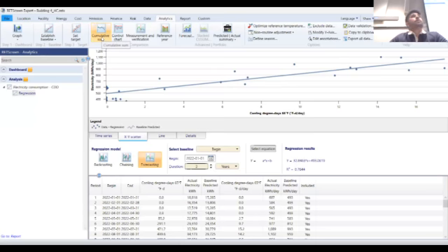Actually, let me back up. What we're doing is we are trying to use a baseline to predict what the consumption in 2024 should look like, and then comparing with the actual data that we have from Portfolio Manager. And the difference will either be energy saved or energy increased, right? That's what we are trying to plot. A regression analysis will help us with that. It will help us predict based on 2022 what the consumption in 24 should look like.